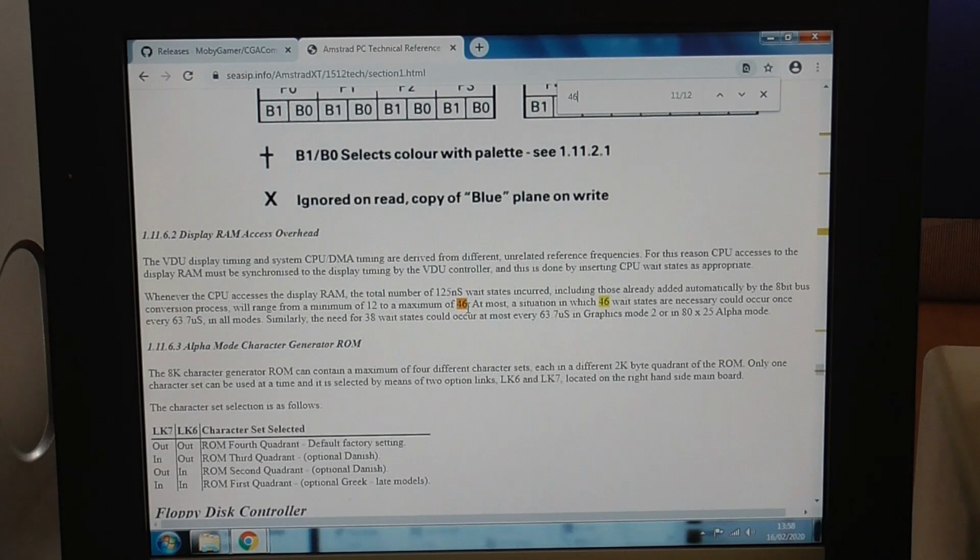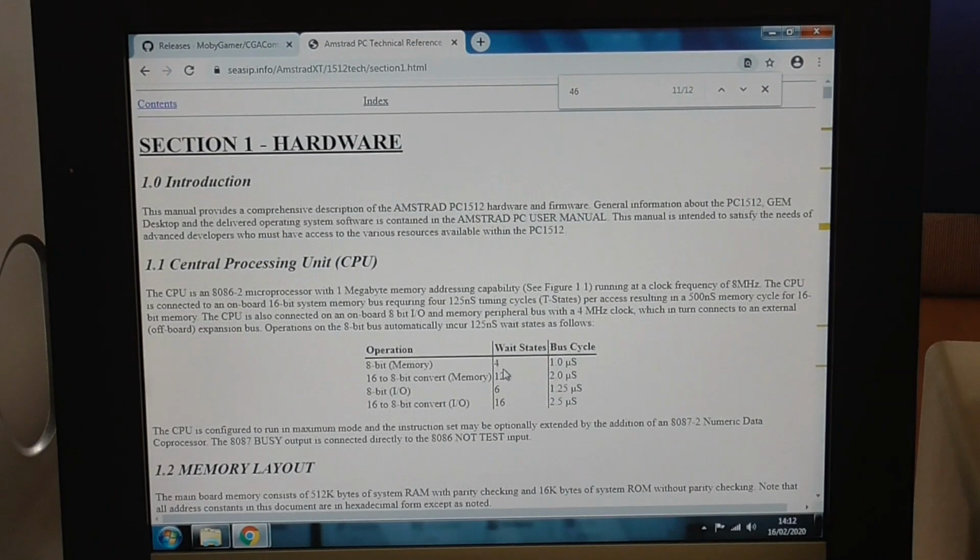the Amstrad PC1512. So my first idea was to try and find a way to fill these wait states, especially the very long 46 cycle one at the end of each raster, with other instructions to do something useful, for example drawing a picture on the screen. So the first thing that I did was to try and figure out how many 16-bit memory writes I can do per raster, and it turns out that I can do 7 of those. In other words, you can only write 14 bytes to the CGA card every raster.